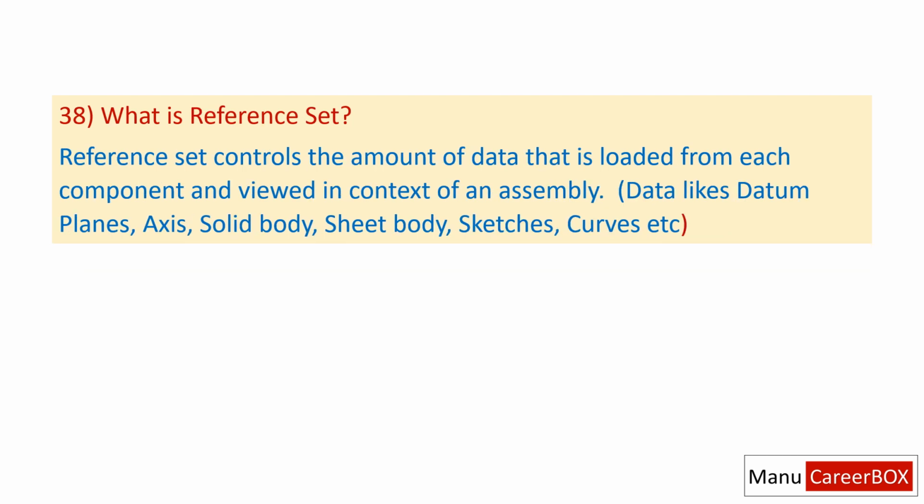38. What is reference set? Reference set controls the amount of data that is loaded from each component and viewed in context of an assembly. Data like datum, planes, axis, solid body, sheet body, sketches, curves, etc.